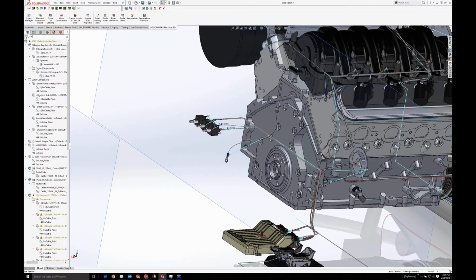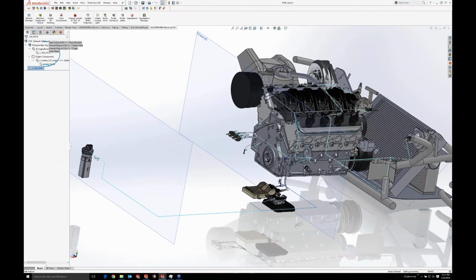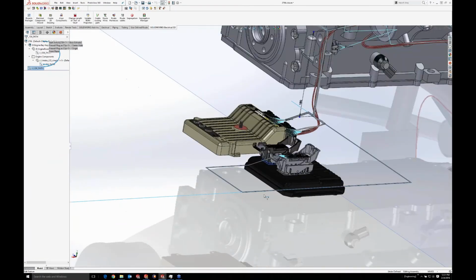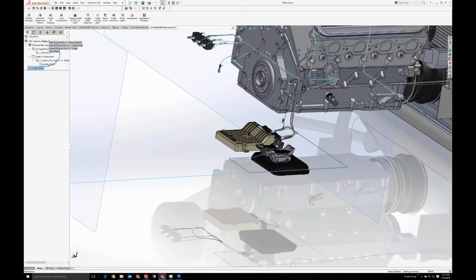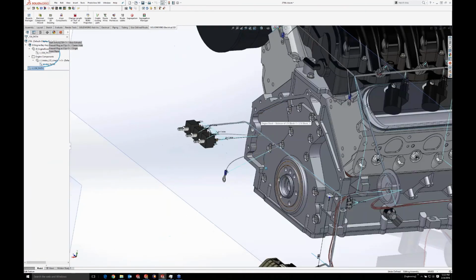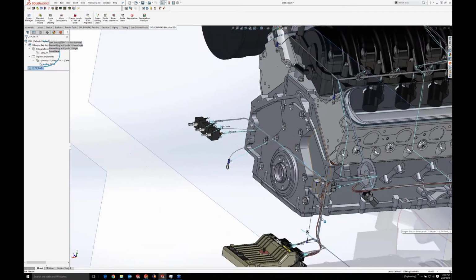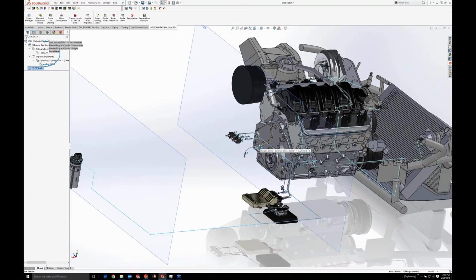Full disclosure, there was some 3D sketching that went on before we came in here. So you can see this one. This is the EW path that it's referencing in my top level. You can see the dotted lines where it comes around. I gave SOLIDWORKS a little 3D sketch saying, try to route your wires over here. And that's why, oops, wrong way. I don't know if you can see that very well over the webinar, but we've got some dotted lines here that just show it's orthogonal, it's only lines, nothing crazy, but that's giving SOLIDWORKS an idea of where I want to route.